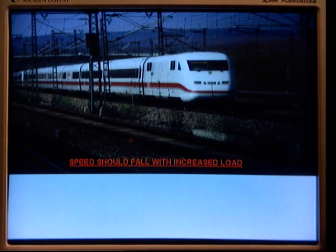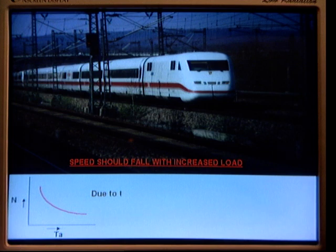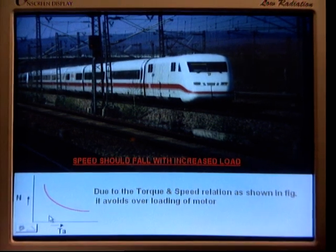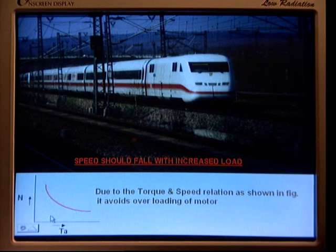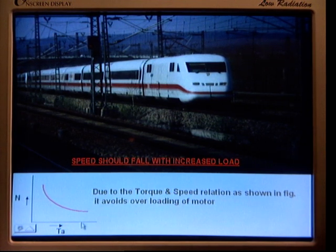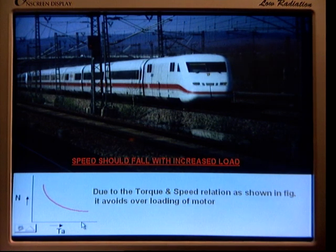Let us go to the next characteristic. Speed should fall with increased load. If you design the traction motor, it should have the following characteristic. You can see the speed-torque characteristics. At starting, the torque developed is more and the speed is less. When the load on the traction motor increases, the speed will fall. This is a very good characteristic, as it avoids overloading of the motors.